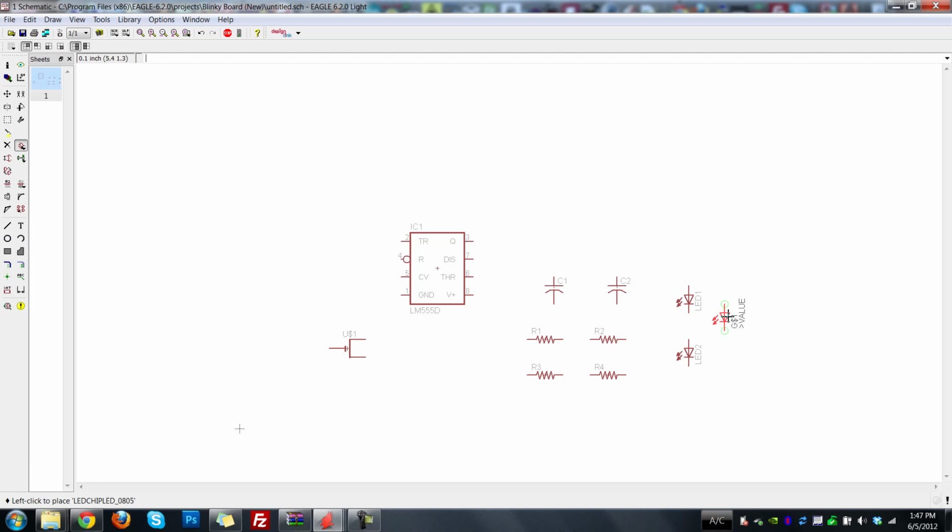Now that you have all the components set up, the next step is to actually wire them all together. Let's start by getting everything positioned where we want it. Click this Move an Object button up here. Single left click on an object, move it around, and then click again to drop it. If you want to move a group of objects at once, you can use this selection key up here to define a group. So click and drag to define a group. Then make sure that this is selected again. And now instead of left clicking, you're going to hold Control on your keyboard, right click, and that will move the group. And then you can left click to release it, all while holding Control. That allows you to move a group of things.